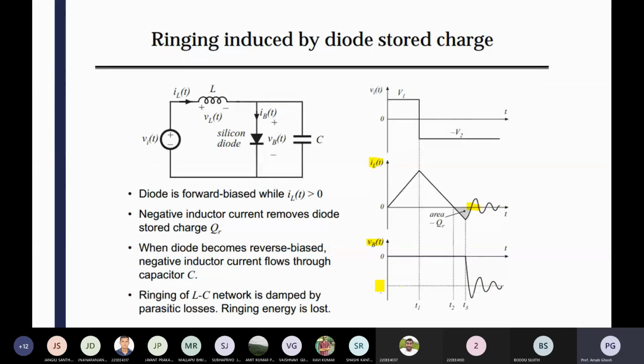It is like your step response in a control system. Normally in a second order system, and it is also applicable to a third order system, you give a step value for checking your system stability, oscillations and other things, meaning transient stability. If you have a plant transfer function and you apply a unit step value to your plant in a closed feedback path, you will get some oscillation around your set value.